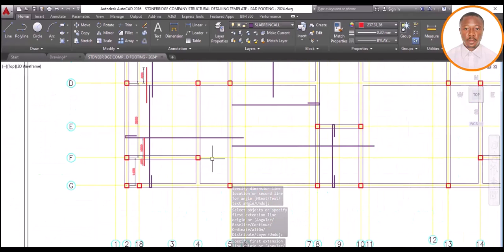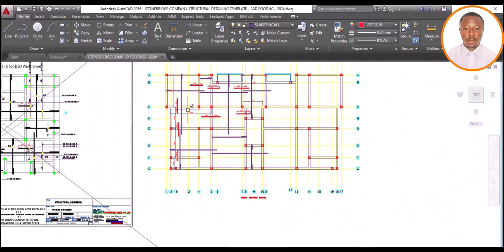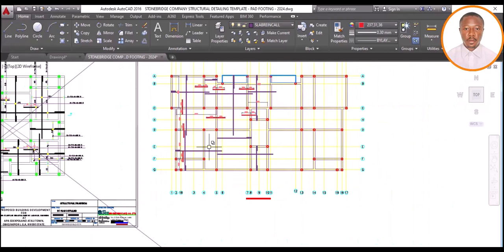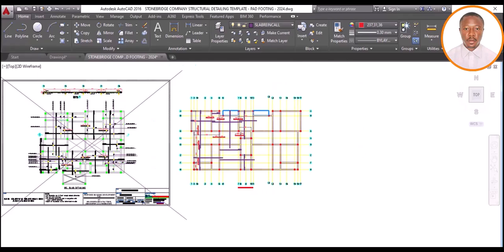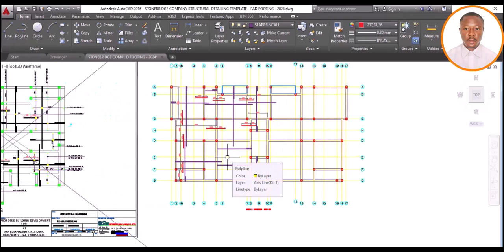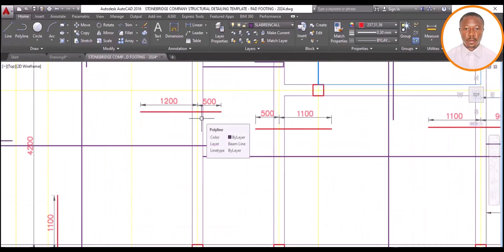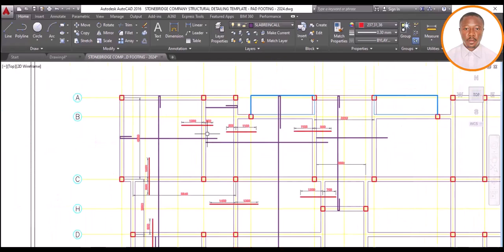So any other one again? When it comes to the x-axis, our top reinforcement, we are done. Okay, I think that is all. So we are done with our top reinforcement. As we have said, we are done with part 2 of our top reinforcement. As you can see, we have finished indicating our top reinforcement and the principle behind it, which is 25% of your slab length will become your top reinforcement into each slab.